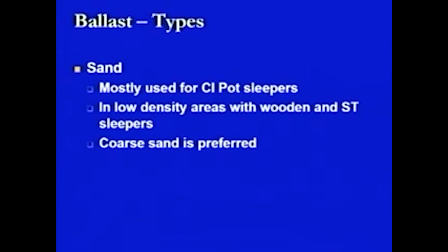In all these cases, coarser sand is generally preferred instead of finer sand, which has a tendency to move away with the weathering agencies. The coarser sand will remain intact, and at the same time it will have a better drainage property.